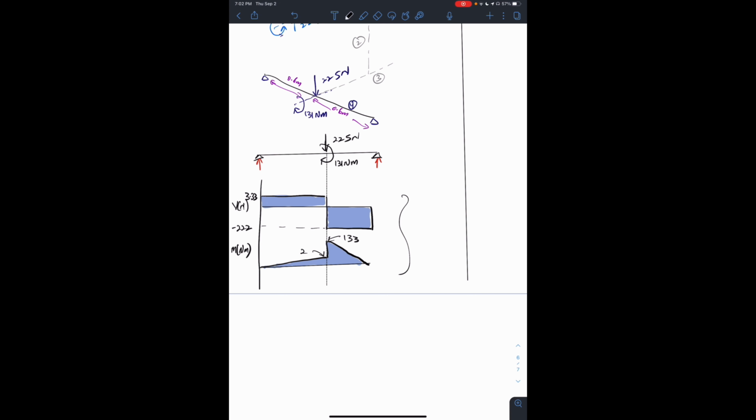If you notice, the shear force diagram is not symmetrical, even though the distance between the middle and the forces there is equidistant, 0.6 meters, and that is because we have this moment being a part of the system now. So you have to consider that moment when finding the reaction forces at either end. So that is why the shear force diagram looks like that. And the bending moment diagram, because we have an applied moment, will be represented as a jump in the graph.